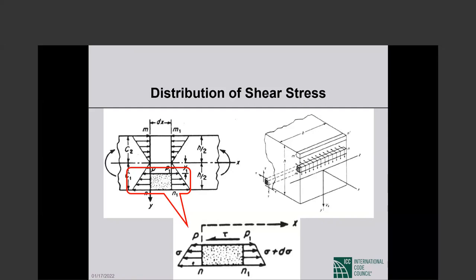I will read again. Thus, we must observe at the outset that there will be horizontal shear stresses between layers of the beam parallel to the neutral plane, as well as transverse shear stresses between cross sections, and that at any point in the beam, these complementary shear stresses are equal in magnitude.